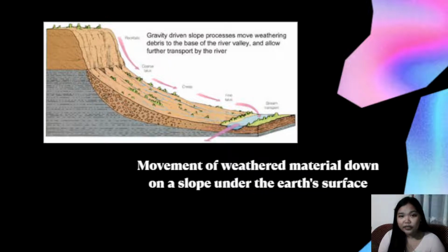The water that is in the zone of aeration, where air exists, is called vadose water. And the water that is in the zone of saturation is called groundwater. For all practical purposes, all groundwater originates as surface water. Once underground, the water is moved by gravity. And the boundary that separates the vadose and the saturation zones is called the water table.